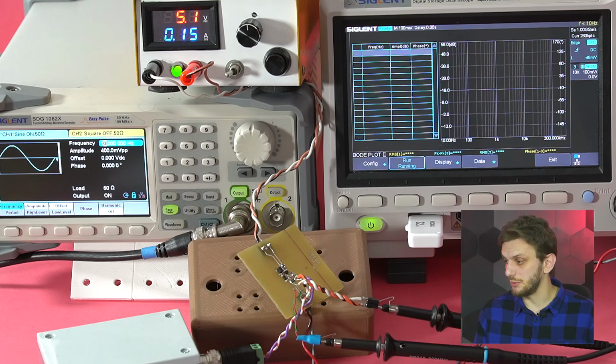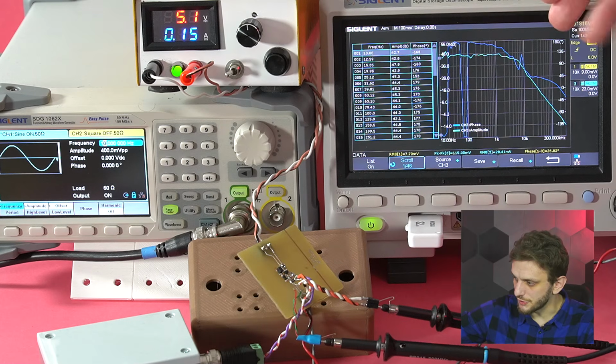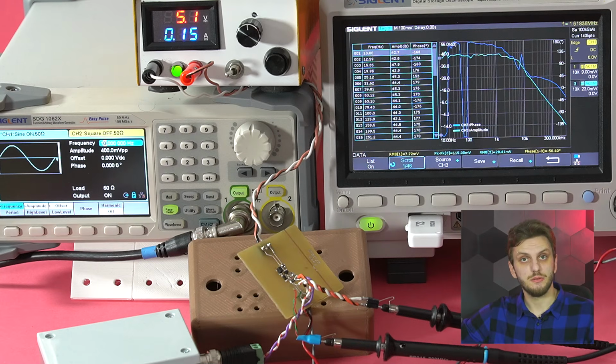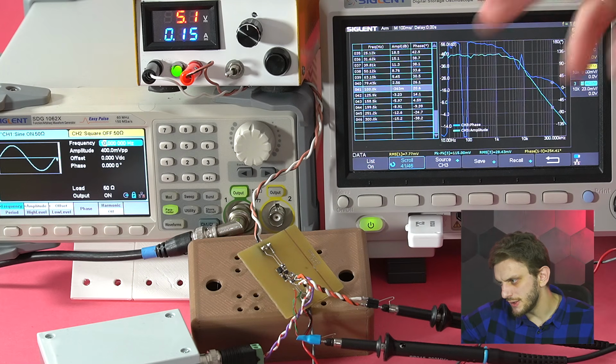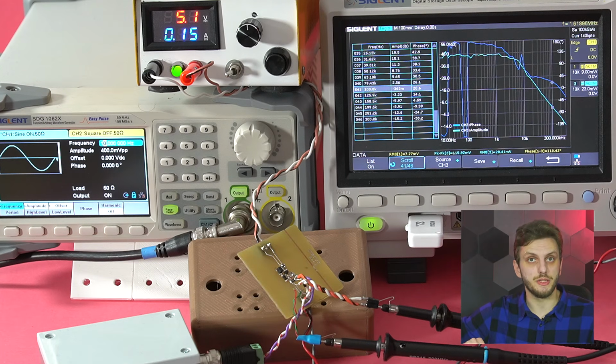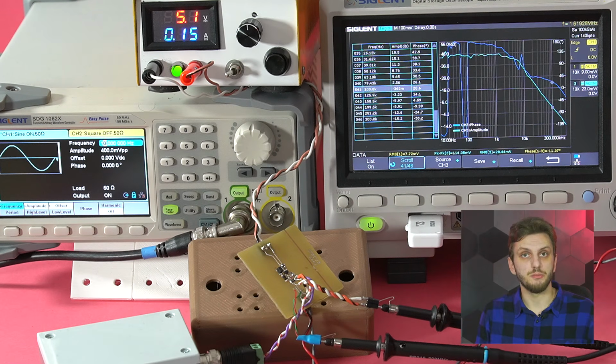So if we run the measurement like this, we are getting a cleaner result, so the gain doesn't jump around as much. It's a far more stable line. And if we look for our crossover point, it's again in the same 100 kHz region with the same phase margin of about 20 something degrees. So this should be a more accurate result. And anyway, if you want to get a clearer picture, you can always perform more test steps. So right now I only have 10 points per decade, but more can be used.